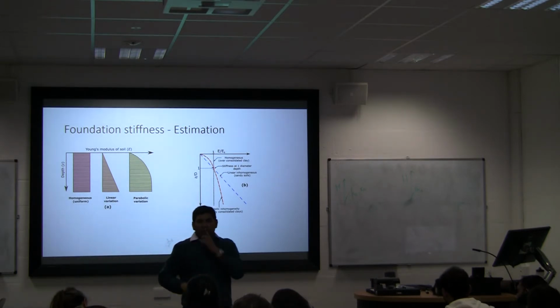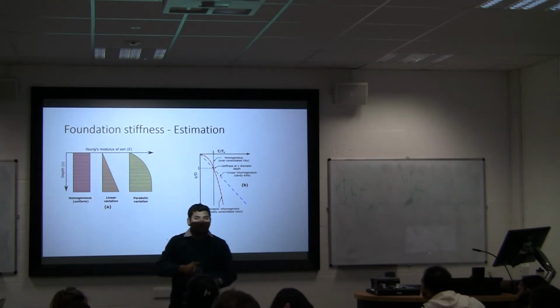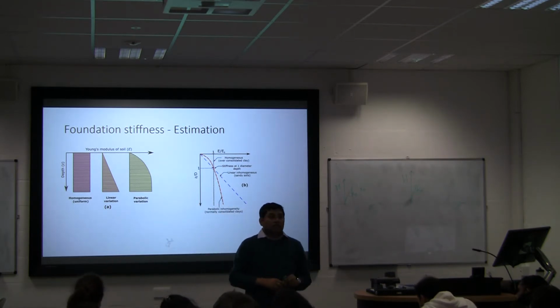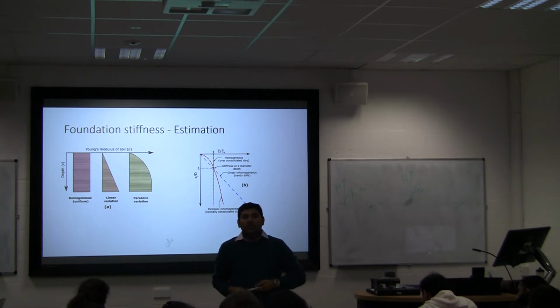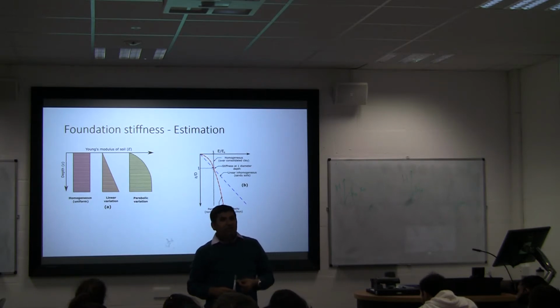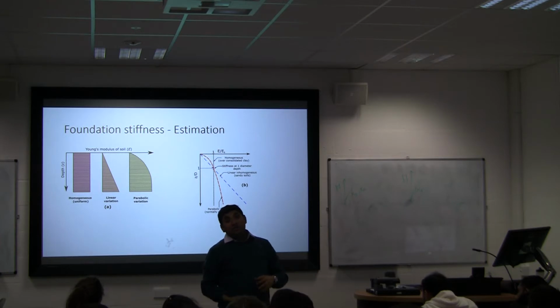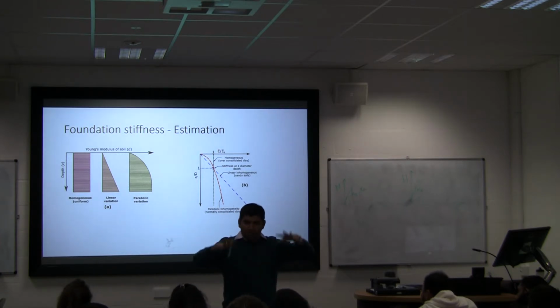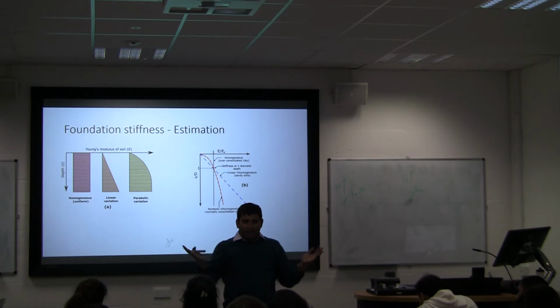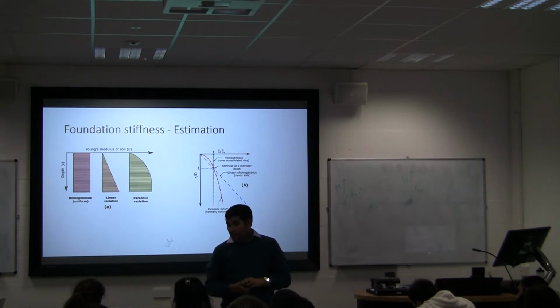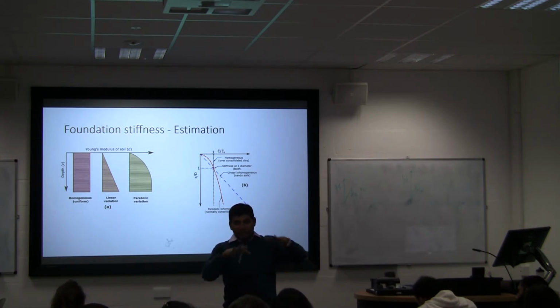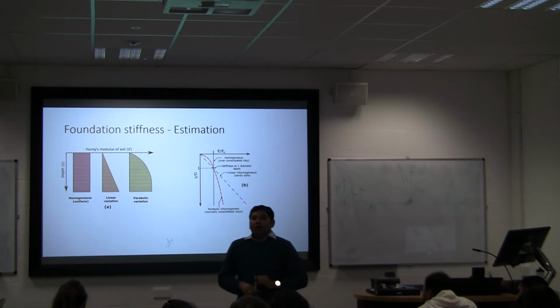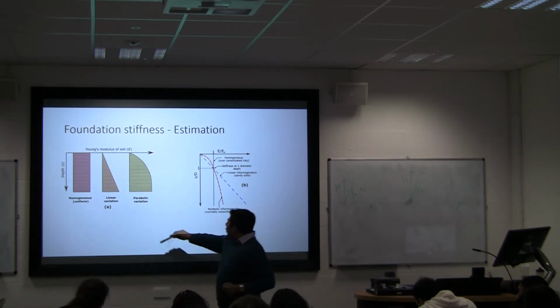Can somebody tell me where we can expect this sort of ground, uniform? Over-consolidated soil. So if it is over-consolidated soil, where can you get that soil? Brownfield soil, yeah. Or some parts of the North Sea, because there was huge ice loading in the ice age, huge pressure was there, the ice melted, so it's now very deeply OCR clay. London sometimes is an OCR clay because there was a huge amount of construction done, right?